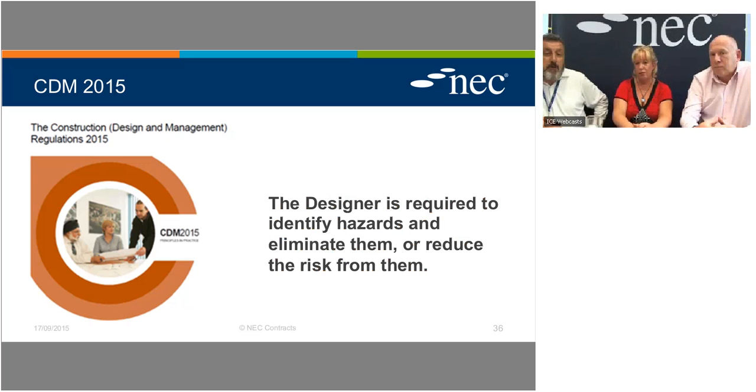Designers are required to identify hazards. In the new regs, they're prompted to eliminate them or reduce them. That was a requirement previously, but a lot of designers would say, well, it's too hard to do that or too expensive to do that, but I'll just flag them up and the contractor can deal with it. But it's been focused now. The tool on that, though, is allowing you to help design out by looking at the BIM model. So you must be able to look at those potential conflicts and barriers and say how we're actually going to work through this to avoid that dangerous thing.